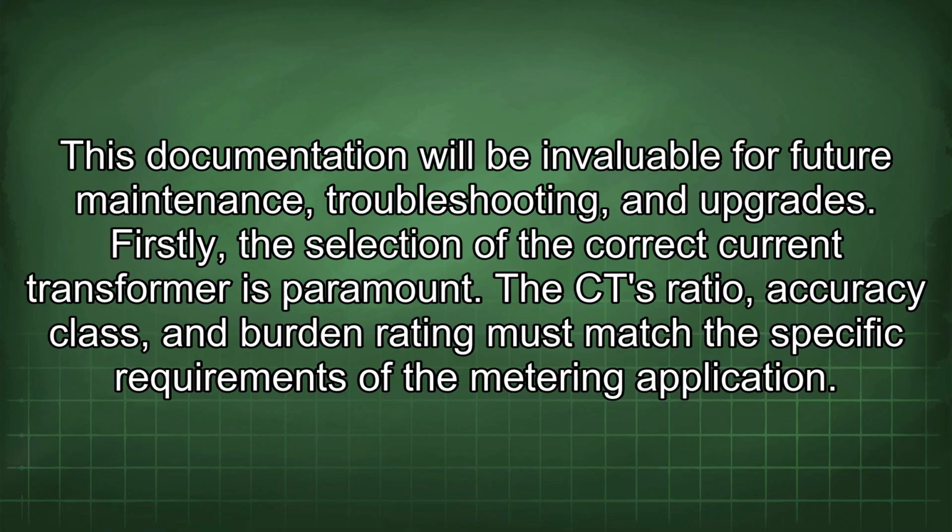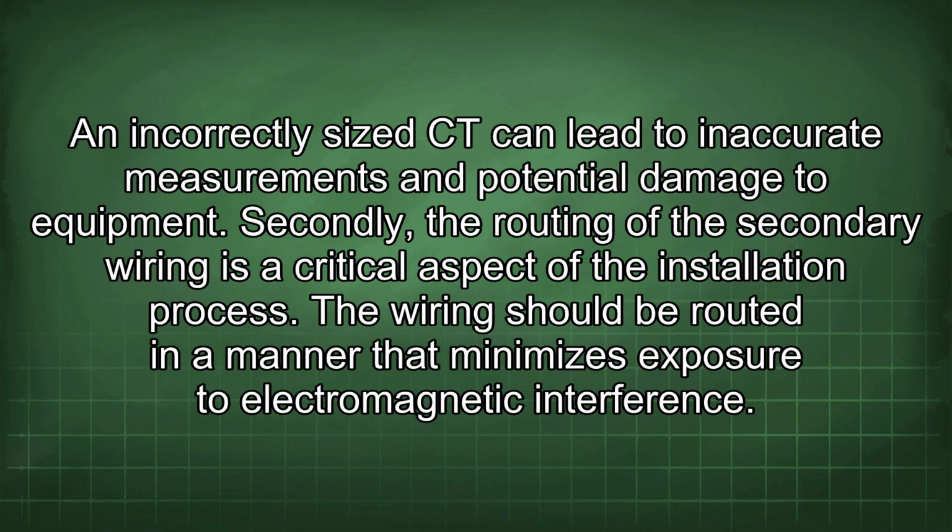Firstly, the selection of the correct current transformer is paramount. The CT ratio, accuracy class, and burden rating must match the specific requirements of the metering application. An incorrectly sized CT can lead to inaccurate measurements and potential damage to equipment.